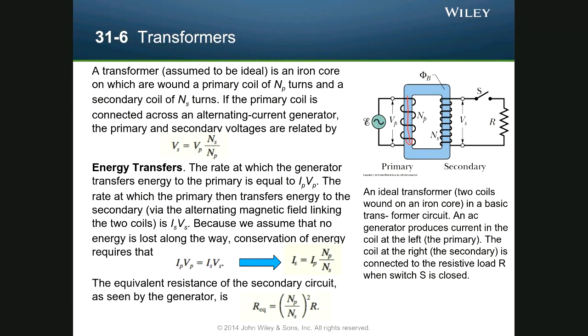But then you oscillate back the other way. As you change and you're going back and forth through here, that's actually affecting the magnetic field through the bar. That means that you have a secondary wrapped coil on the other side of the bar, and you get an induced current. So you have the field opposing the change, and the change will be going back and forth. That will induce an AC current in this secondary circuit, which you can deliver to your resistive load. And you'll have a voltage, a potential difference, across the resistor from the secondary circuit.